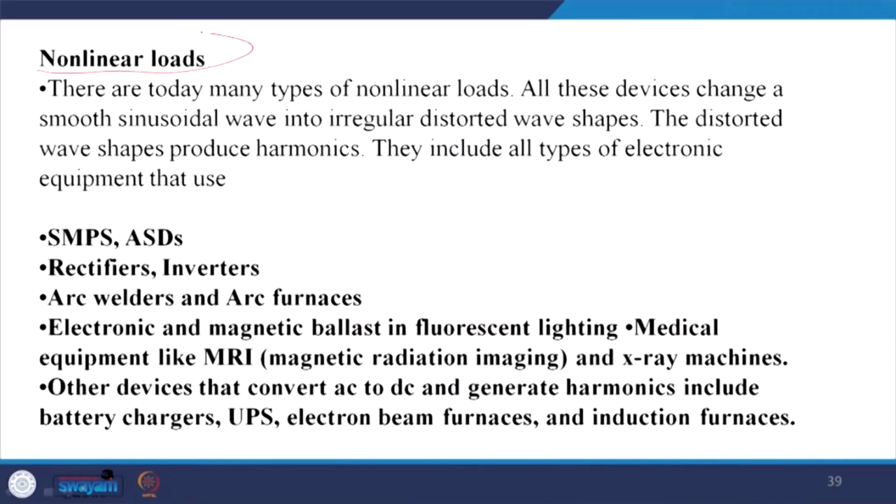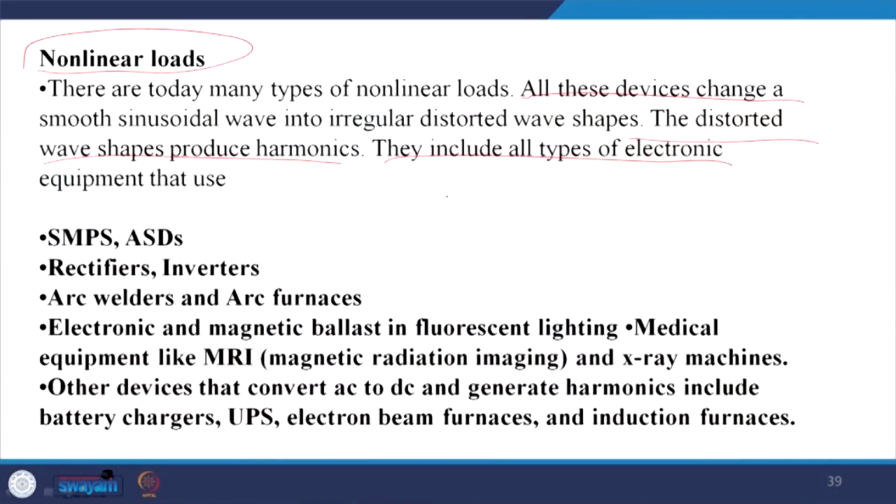Moreover, the nastiest entity is the nonlinear load. There are today many types of nonlinear loads. All these devices change the smooth sinusoidal wave into an irregular distorted wave shape. We have seen a waveform for the input waveform for the adjustable speed drive. This distorted wave shape produces harmonics. They include all types of electronic equipment,